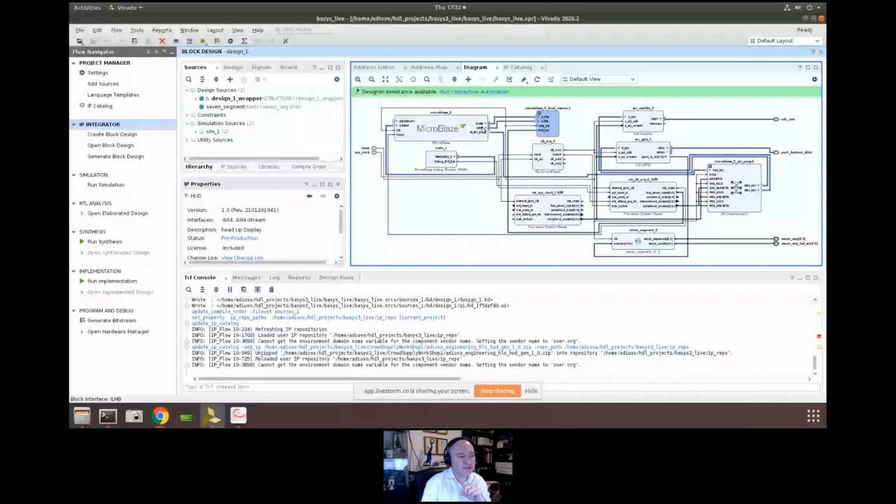Somebody was just asking, is the system clock connected with clock wizard clock 1? Is that okay? So the system clock should come in, and it should run into the system clock 1, and it should go through and create everything else. Just have a locked one go. So that should give us a nice solution.